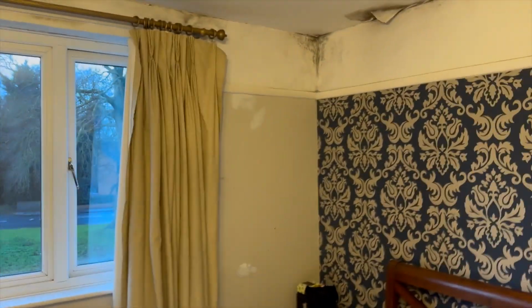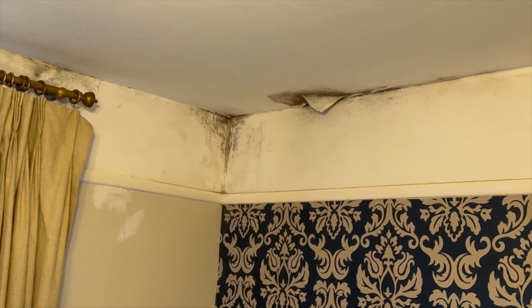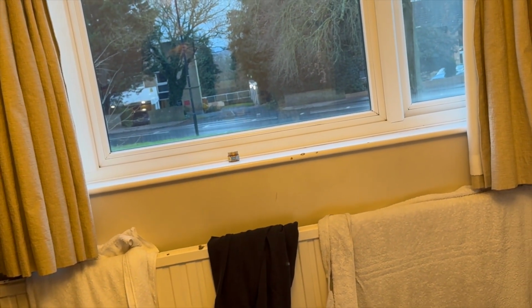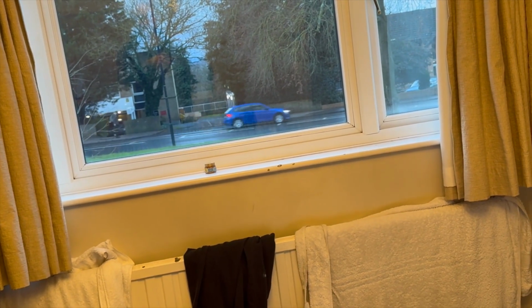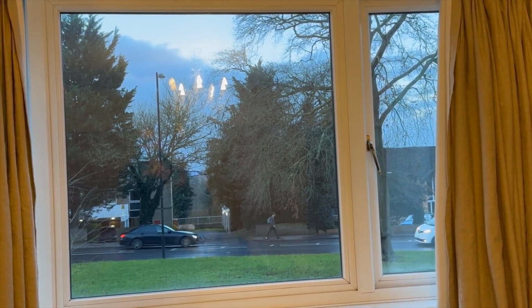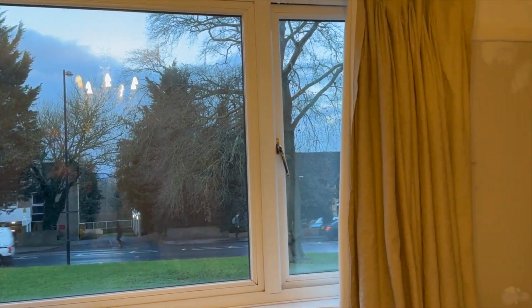You've got mould as you have here. It's primarily caused by excess vapour, made worse by heat loss, heat differential, thermal bridging, and so I'll have a look from both angles. It's all solvable. And there's access to the loft. Through there. If you want me to bring the ladder down, I can bring it down for you.